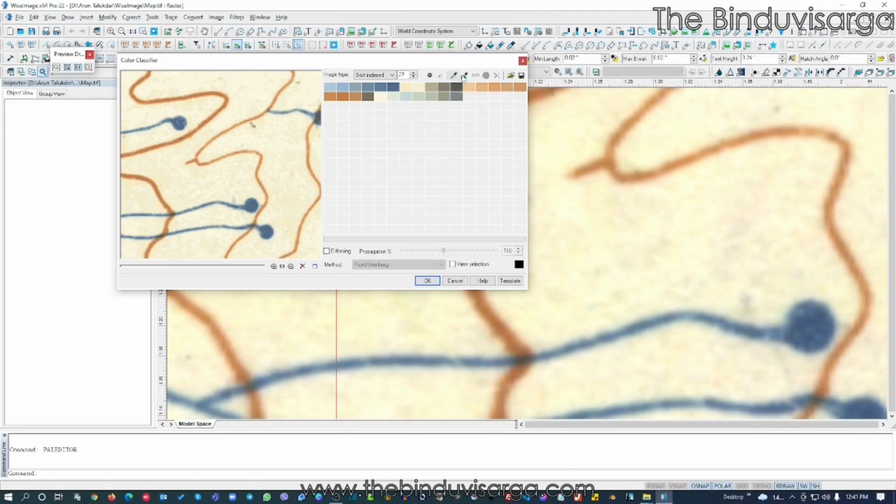So now if I click on this selector, and I click anywhere roughly, and I just hover the mouse without clicking, remember. So just hover the mouse on the image, and then when I finish, I should double click, and now you can see it marked 3 different colors. So it suggests that I have 3 different colors approximately on the background there, and I'm assuming that throughout the background I have the same sort of distribution.